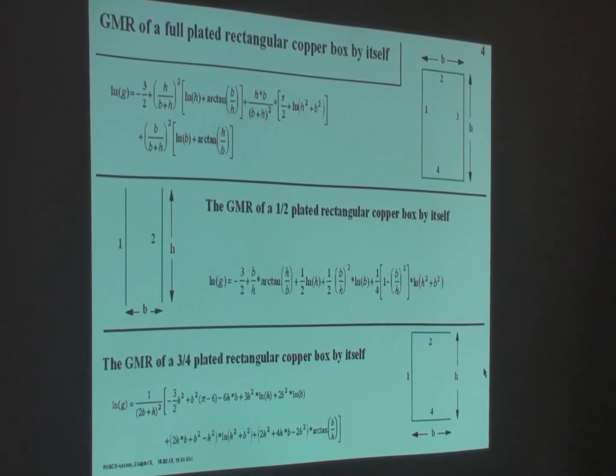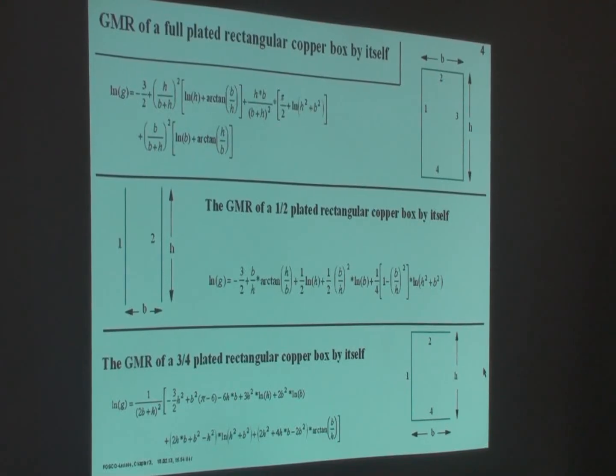Because of saturation of the iron, the permeability is very small, and then the skin depth is bigger than copper. But normally, if no saturation, the skin depth is very, very small.